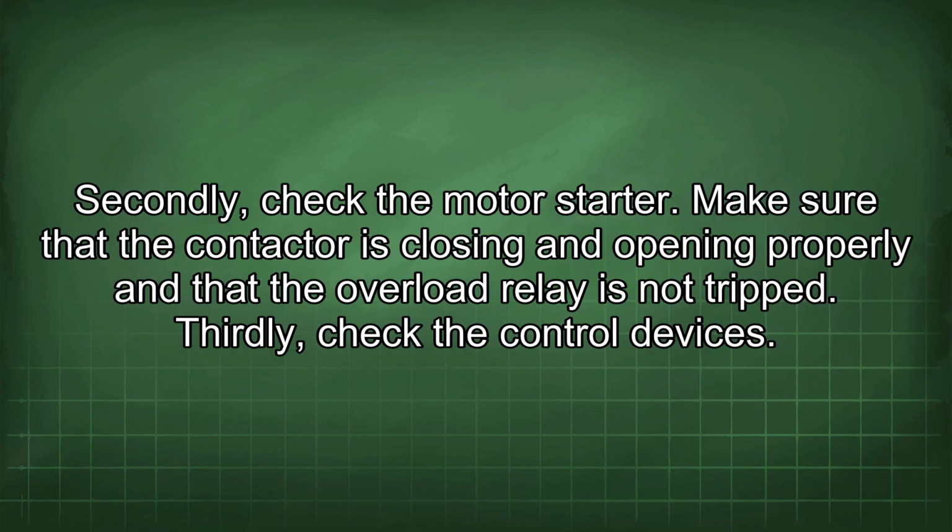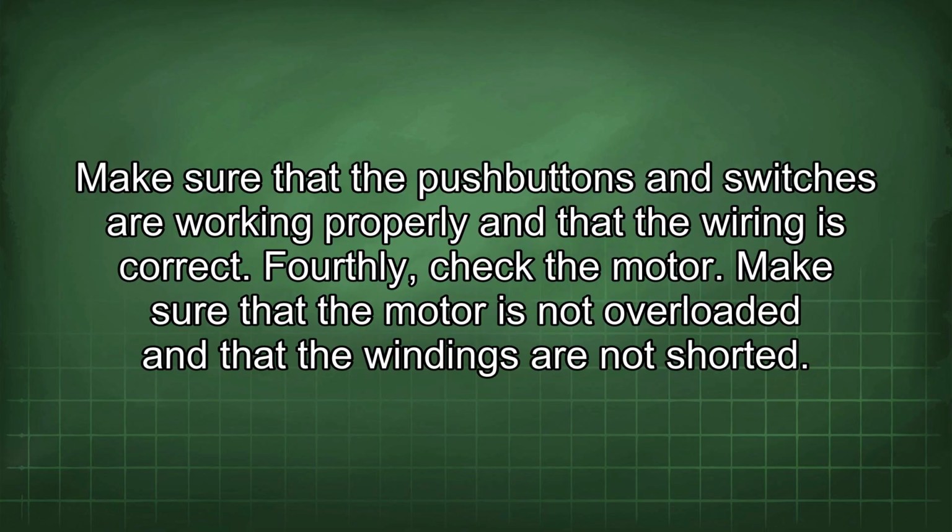Thirdly, check the control devices. Make sure that the push buttons and switches are working properly and that the wiring is correct. Fourthly, check the motor. Make sure that the motor is not overloaded and that the windings are not shorted.